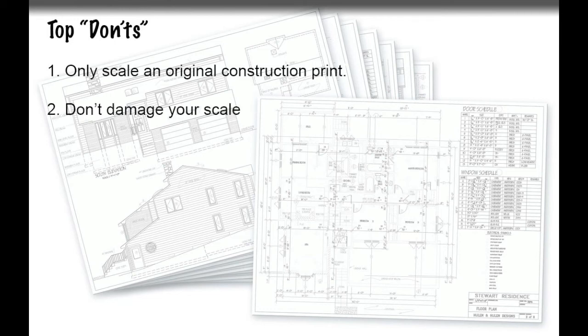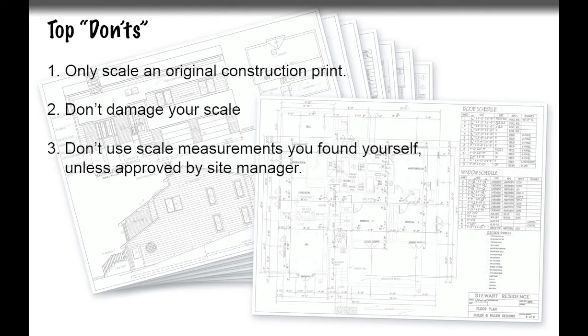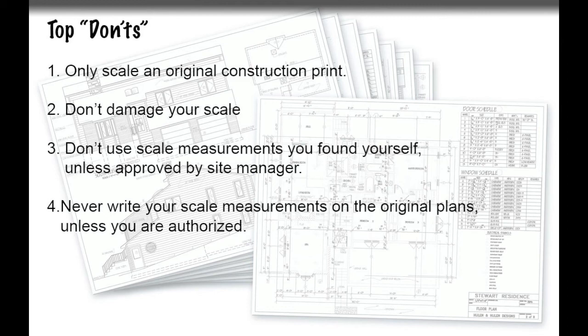2, protect your scales from damage. Indentations on the scales will remove graduation marks. 3, don't use scale measurements you found yourself unless they are approved by the site manager. And 4, never write your scaled measurements on the original approved set of plans unless you are authorized. Ask for a markup copy to be written on. Have the site manager approve your scale before they are used on the job.